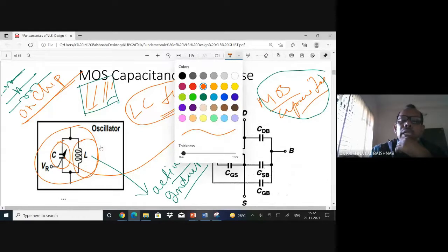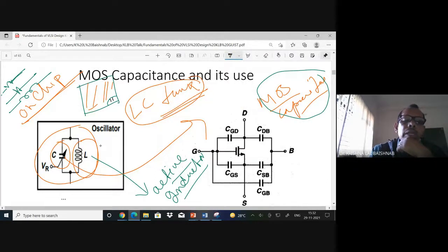This is not advisable. In a die, the entire part is the inductor, and only a very small or negligible part, maybe 1%, 2%, or 5%, is your circuit design. That really consumes my major silicon area, so that's why the passive inductor is not used at all.